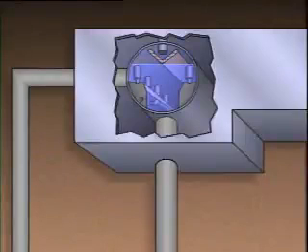In the opposite case, the boiler drum water level would rise. In a short time, this excess water would be carried out of the boiler drum, along with the steam, to where it could damage components, such as the boiler superheaters. Damage from mismatched steam and water flows can be prevented by controlling the flow of steam entering the turbine and the flow of feed water to the boiler.